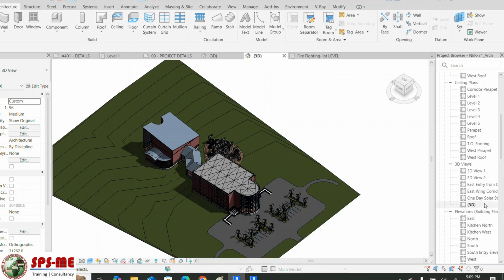Normally on the consultant side, Revit is the software we use to create the BIM models. But BIM has certain guidelines. You may have heard about the LODs and the BIM Execution Plan. If you are on the consultant side, you have to follow LOD 350. That is the world-accepted standard for the consultant, and for the contractor it will be LOD 400, and as-built drawing LOD 500.